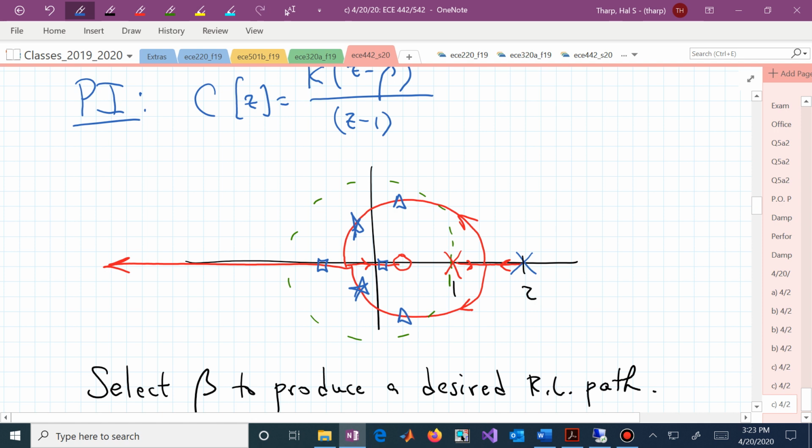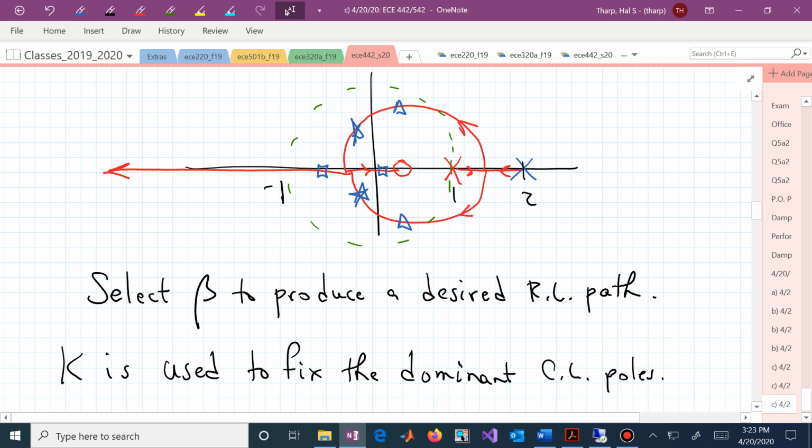For me, I would probably prefer the triangle location, because having poles near -1 sometimes can be problematic, and that's where that leftmost box is going, and it might actually be more visible because that box, if it's close to the 0, may be somewhat annihilated by that 0's behavior, because what do 0's do? They zero out a response. So this is now, though, the one way to select a stable closed loop system.